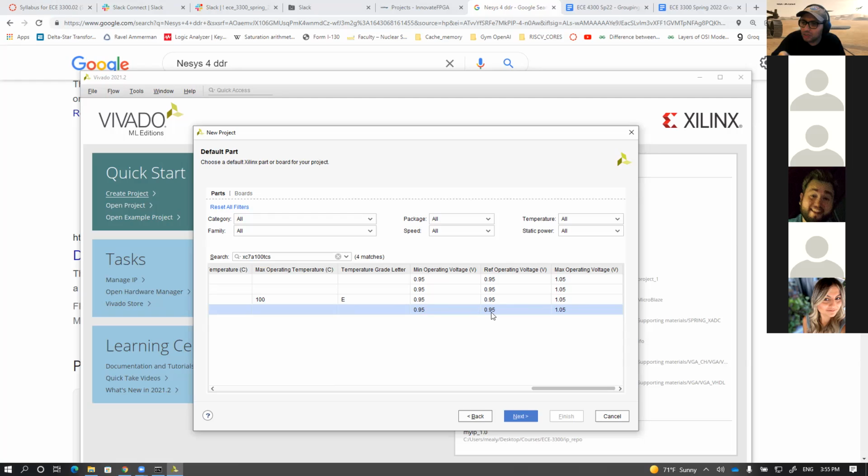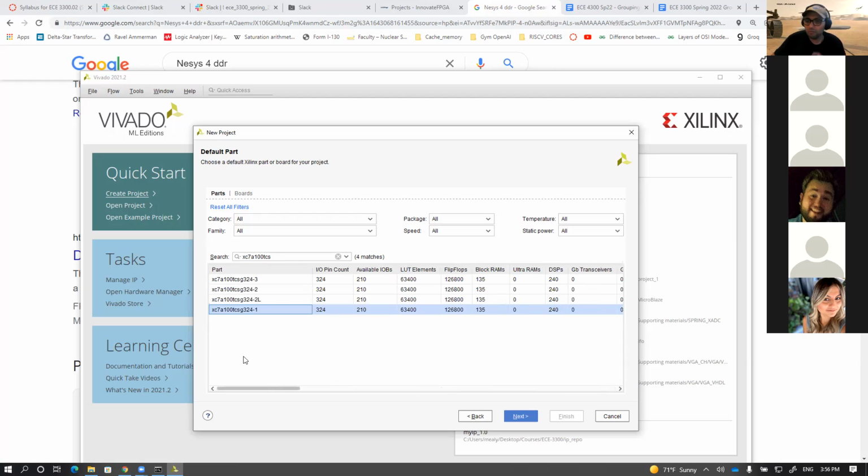That means you can run it with a battery, like 1.5 volts, with a regulator to decrease the voltage from 1.5 to a fraction of 1 volt. Of course, on the chip there are regulators to help you communicate with 3 and 5 volts and pass to the chip this amount of voltage, 0.95. The rest of the IPs may need 5 volts and 3 volts. So far, so good? Or do you have any question?